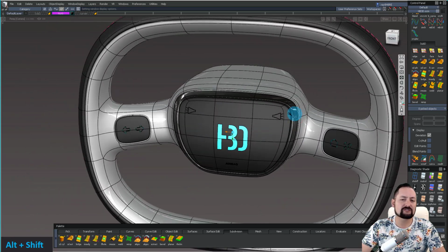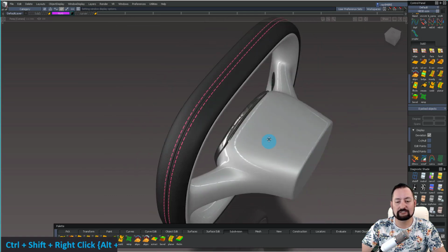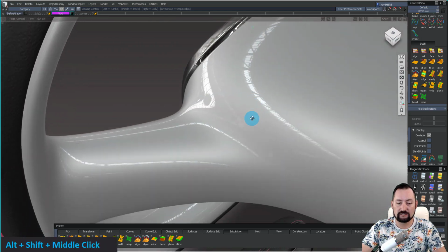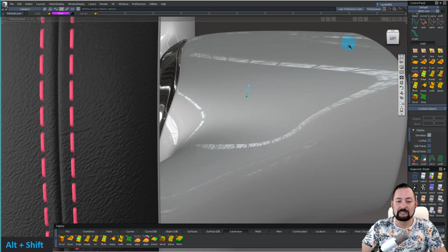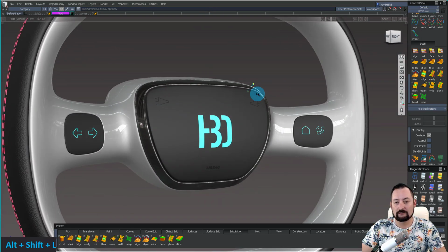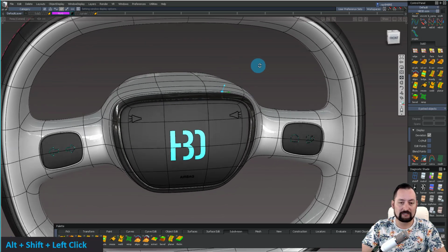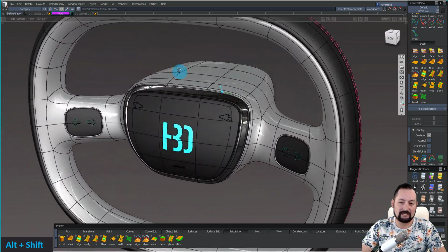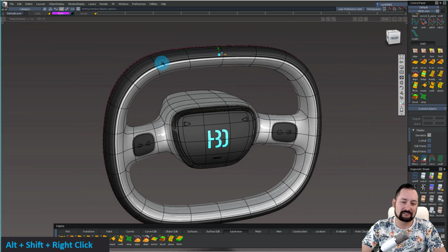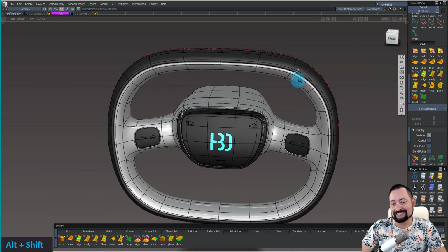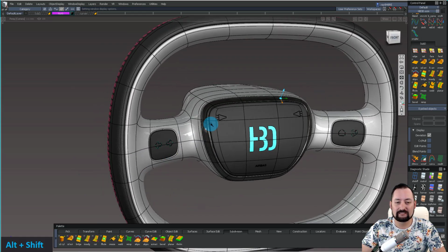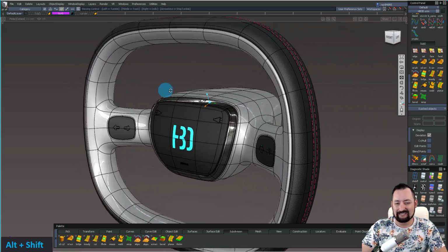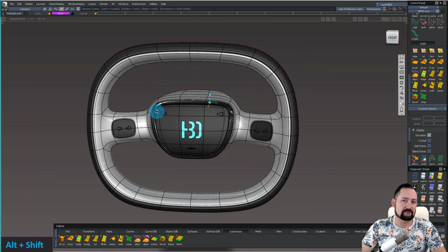The reason I chose the steering wheel is because it's a very organic shape, and it's almost more difficult to model this in Nurbs, especially when we're talking about these sorts of transitions. So Sub D is actually becoming quite a useful tool inside of the modeling industry. I don't know if people would use this in the end result, but especially for things like steering wheels or seats, things that are very organic and are going to be wrapped in leather or used with very soft textures, it's definitely a much quicker workflow.